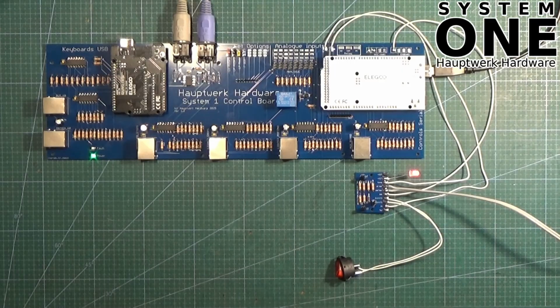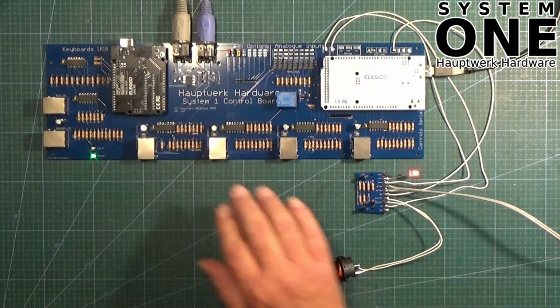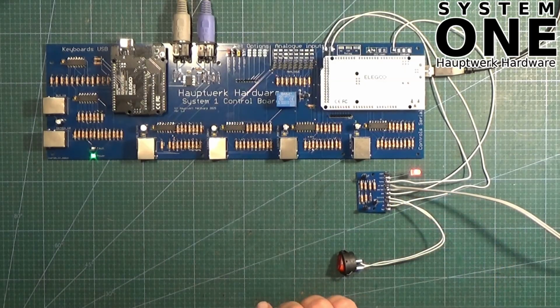Also, just in case it doesn't, the System 1 control board does that internally anyway. As soon as it sees this switch operated to switch off, it will switch the LED back to red anyway, regardless of whether it receives the MIDI to do that, because it knows now that you're in the shutdown process. So that's that bit of it.